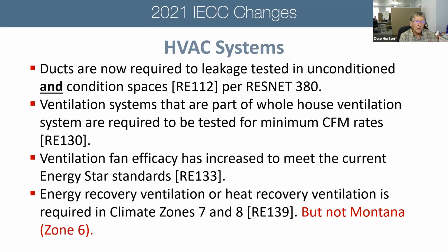And this I thought was interesting. The energy recovery or heat recovery is mandated in the 2021 for zones 7 and 8. It's not mandated for Montana, but I thought it was significant that the IECC now is requiring heat recovery for at least slightly colder climates than Montana. It's kind of like writing on the wall.